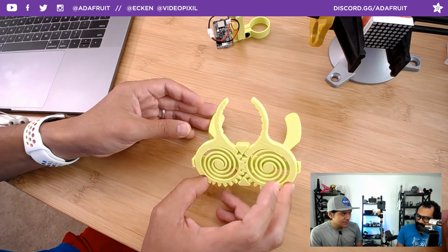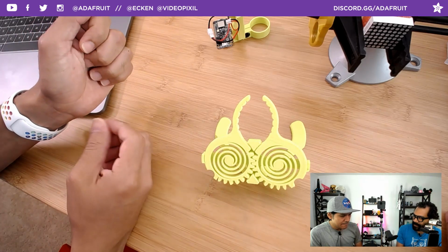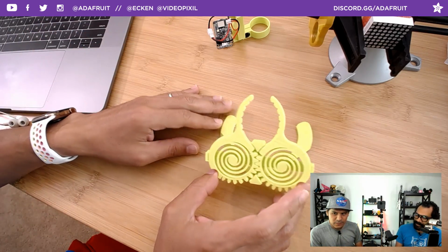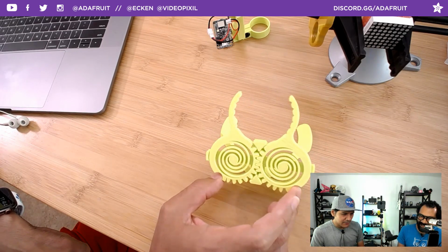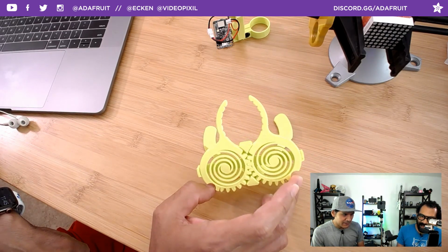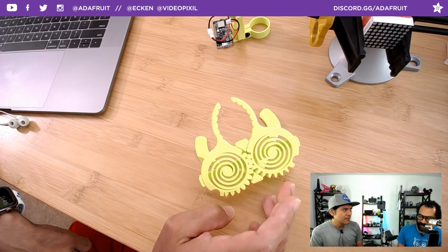I had to redo the way the Z rods work, because I don't have backlash screws on it, so I had to re-level both to make sure they were even. I wish it was just settings, but it definitely comes down to maintenance and swapping out parts that might have been faulty. It's been like a year and a half since any of those have been looked at.